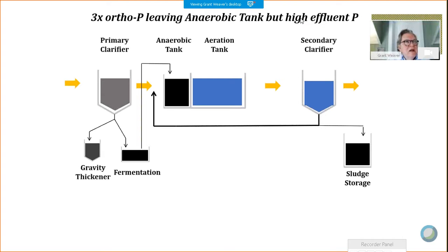So you can't turn them off and turn them on every 6 months. So maybe cycle them on once a day, or every 6 hours, enough to resuspend the materials for a short period of time so that you don't lose all your solids, but for the majority of the time create a nice anaerobic condition.